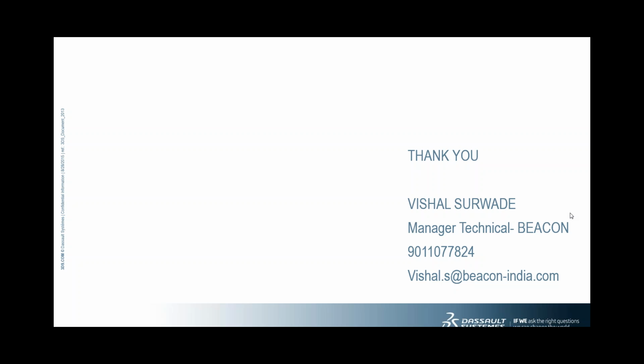Okay, there is a query like how do you define the datum? This seems to be a very generic query. It's not related to MBD. You need to go through some of the DimXpert lessons or GD&T lessons. There are different rules for defining the datum. In this case, in SolidWorks, we have DimXpert and we have annotations through which we can go and define the datums.